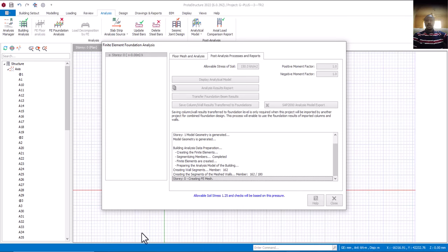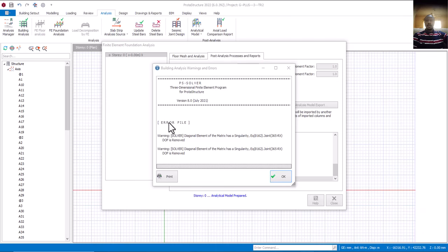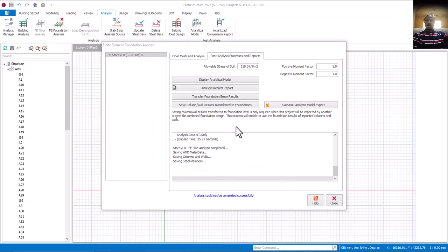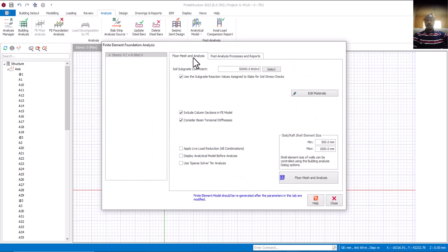Since you have seen it before, let me just pause it. Let me put the length of this video, because we have to continue watching. You can see it's still coming up, which means that the issue now is no longer our space over. So what is the major issue? Come back to this place. The major issue is where you are saying include column section in the FE.